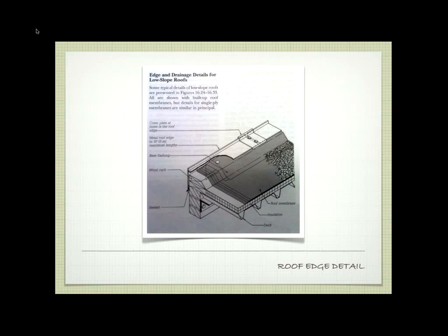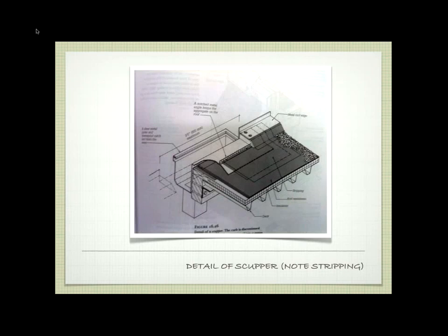In terms of edge details, okay, assuming you're not trying to flow water off a particular edge, and we're collecting the water somewhere inside the site itself, we have to think about how we fold these variety of layers up such that flashing can come over them, so that if water falls here, it's going to flow down over our layers and into the roof itself, right? Again, it's the same principles of all roofing. We need to make sure that water flows through.